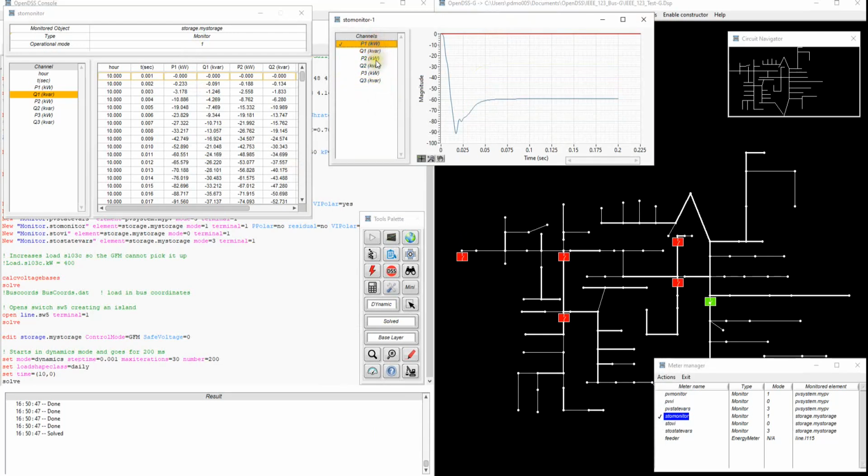We can see that the active power was initially very high when starting the microgrid, kind of black starting the microgrid, and then it went down because of the entrance of the PV system. So the PV system evaluates if the voltage conditions at the terminals are correct, are adequate, and then starts generating. That's why we're seeing this behavior here. So we have two different dynamics, the storage dynamics and the PV dynamics.